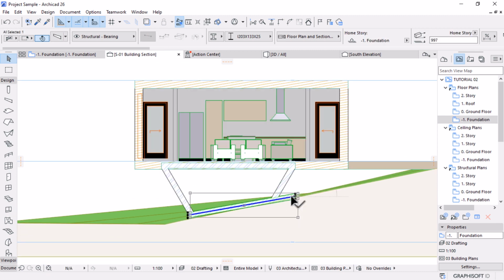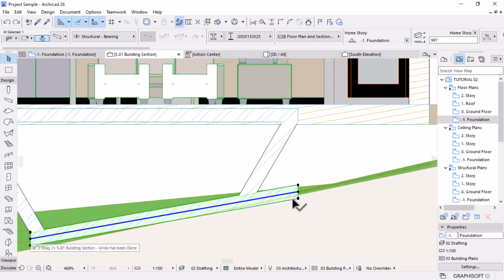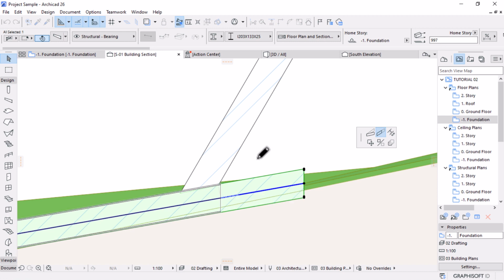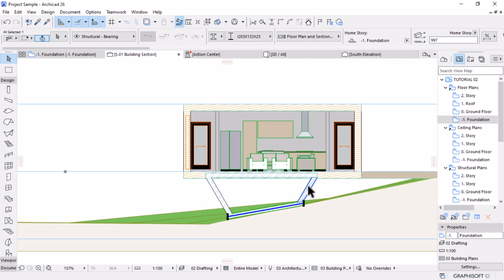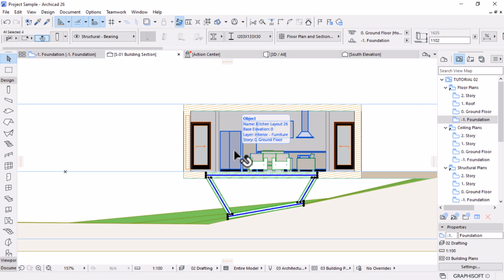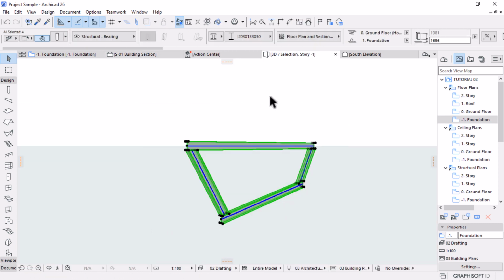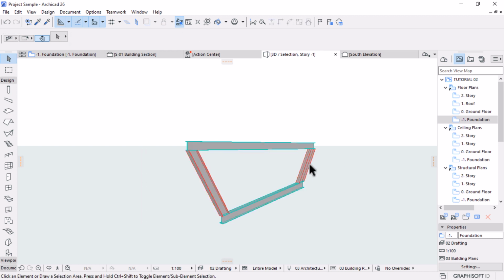And then this has to be also, no, okay, let's undo. I want to stretch this to be right on the edge like that. Once you're done with this, let's group them to be a one unit. Unfortunately, you cannot group on 3D on a section. I would hit F5 to isolate this gentleman, then select all of them, hit Control D.